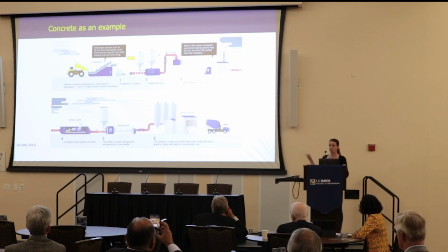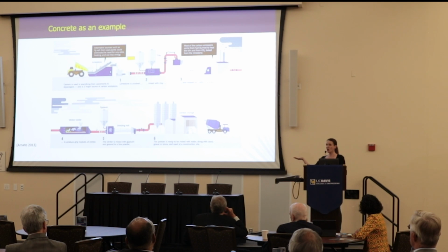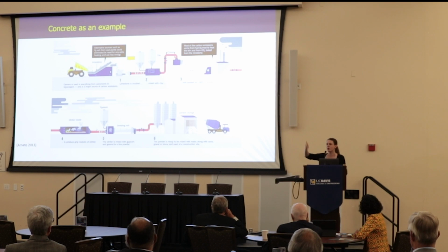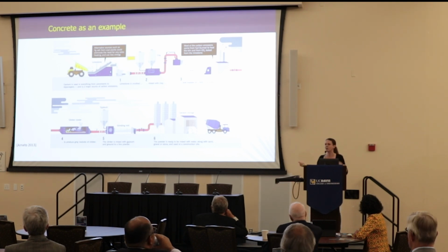When we're producing cement, the way we manufacture it is we take limestones and clays. We use the limestone for the calcium, the clays for the amorphous silica that we need. We decarbonate our limestone. We basically take calcium carbonate and then turn it into calcium oxide, which means we already shoot off a fair bit of carbon dioxide that was otherwise in a nice stable mineral. We then continue to heat the material to form calcium silicates. Those are the hydraulic compound that can then interact with water, pull together the aggregates.